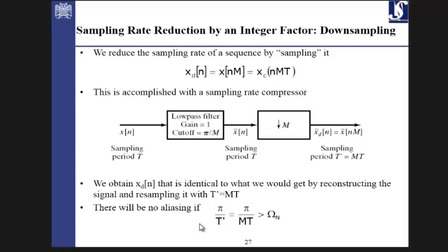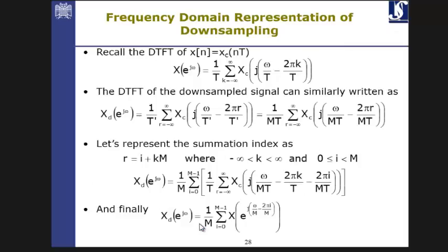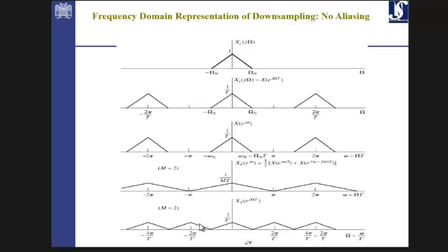Normally for the downsampling, as you said, it boils down to loss of information. And what really happens is that we need to have a filter at the beginning. That's the decimation filter, or the entire process is called decimation, which means low pass filtering plus downsampling. The entire system is called decimation. I will come back to this after I explain everything graphically, which is more representative.